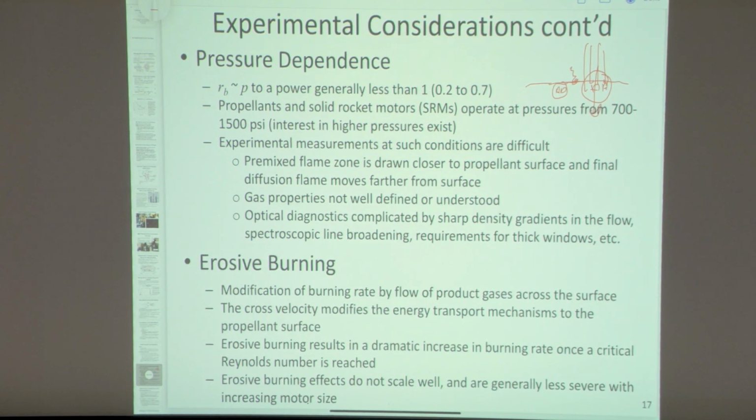So all of a sudden, this diffusion flame gets extended to a higher location at higher pressure, whereas the little particles down here can sort of pre-mix with the binder as it decomposes. And this flame right here then becomes like a pre-mixed flame over the binder. And it remains basically the same. So you change the structure of the flame burning process also as a function of pressure.